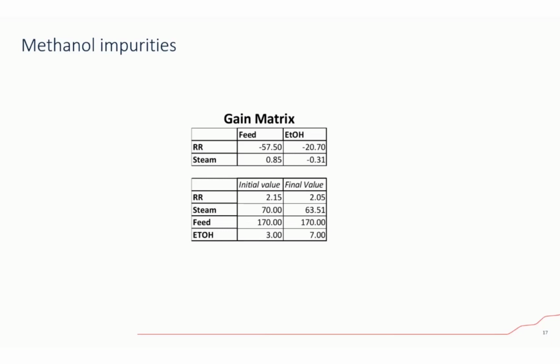If your base layer control is not working well, then chances of your APC correcting for that are not that good, especially because the main job of your base layer control is to reject disturbances that APC will most likely not be able to reject in a timely fashion. What's most important here is time. A PID controller runs every second, every half a second, depending on how you configure it. Obviously, if you have a compressor control, it's every 50 milliseconds or whatever.